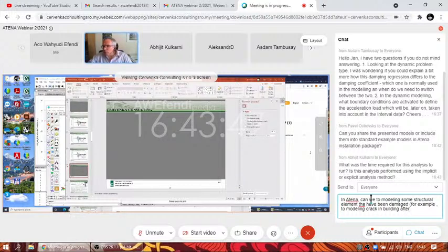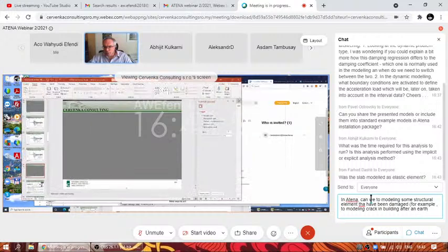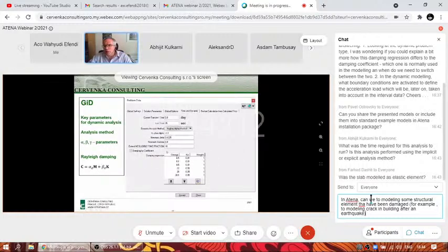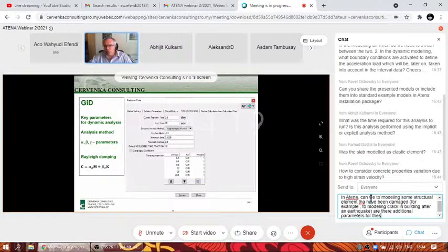Well, this is, of course, a big and difficult issue. Typically, I think we have to make some engineering judgment here. Typically, I think the approach is that we consider something between 1% damping to 5% damping. But this is my understanding. This is the typical situation.